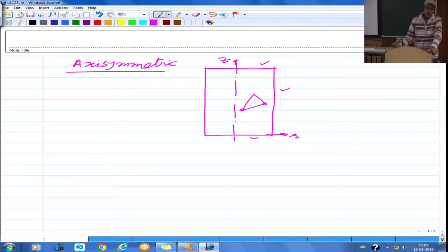Again, whether a 3 noded or 6 noded triangle, or a 4 noded or 8 noded rectangle, how to decide that? That comes from when you want to solve the entire problem. You discretize the domain into a number of elements, and you have to make sure that the number of elements is sufficient to give you an accurate solution.